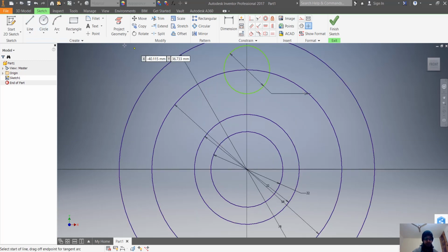Okay, so let's make a line. Click here and click here. Here we have a line. Now offset this line. Oh, it's asking. Oh, nice. I like this. 3. Again offset this line also. Again 3. Look how easy it is.